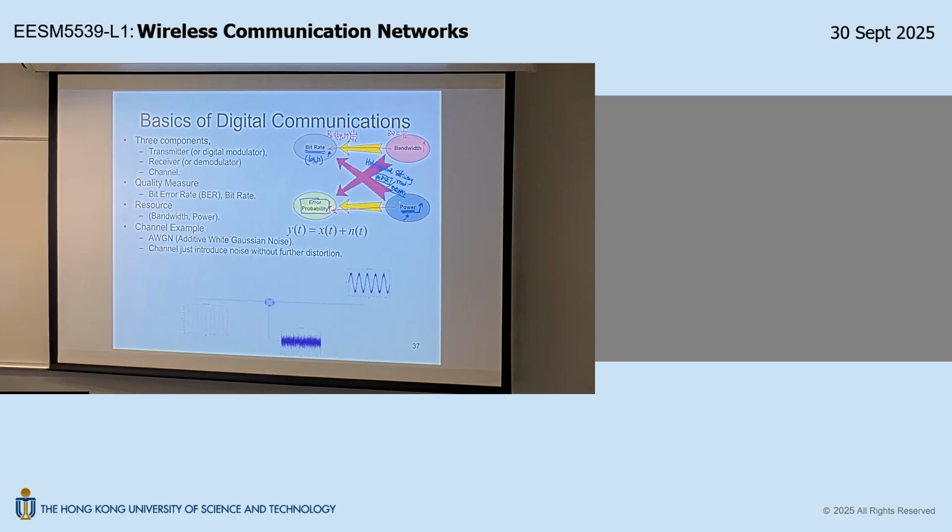So that means, for example, usually for Wi-Fi or some handheld devices, the power amplifier has an average power rating. So usually the average power is 1 watt. 1 watt means 30 dBm. Okay? So that means the maximum average output power is 1 watt for this kind of amplifier. So within 1 watt average, you are still within this linearity range. You don't have this nonlinear distortion yet, okay? However,